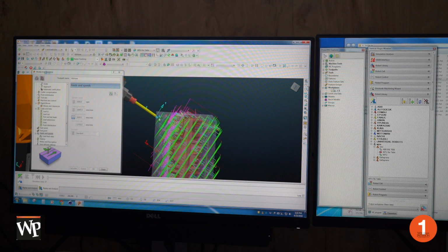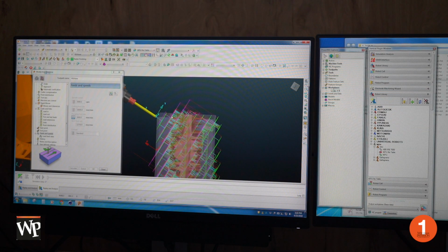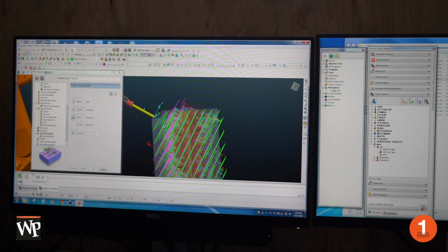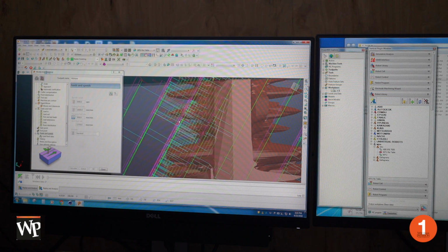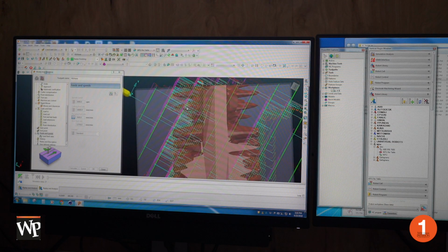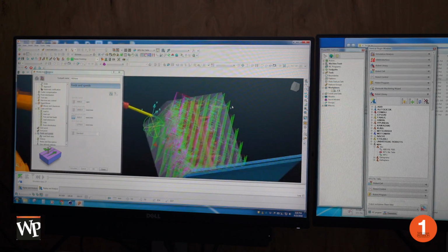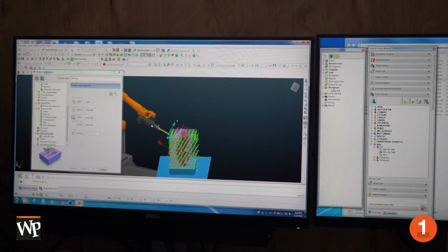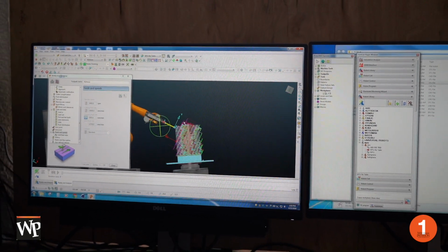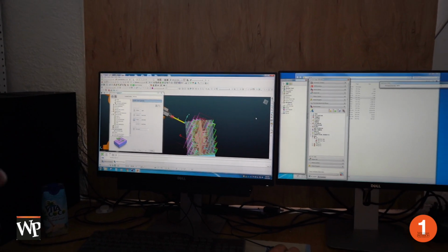So it comes in and it makes concentric circles to cut that area. Then it cuts down and it makes concentric circles to cut that area. And it does the same. Now it starts to hit the model. So then we have the 7mm step up and the areas where it starts to make contact with the model. But right now we can see that we didn't limit it, so this tries to cut all the way through the block. We're going to run into issues with that. So now we're going to limit this toolpath.